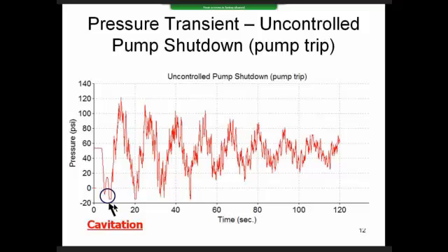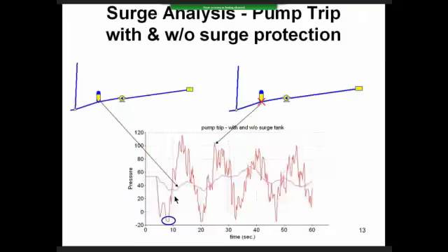And you've got overhead tanks in there that have a couple hundred feet of head. So you're going to get the water column separating due to the inertia, but it's going to collapse and cause a pressure spike. So this is the situation that we see when there's an uncontrolled pump shutdown. What can you do about that? I'm going to talk a little bit more about surge protection.